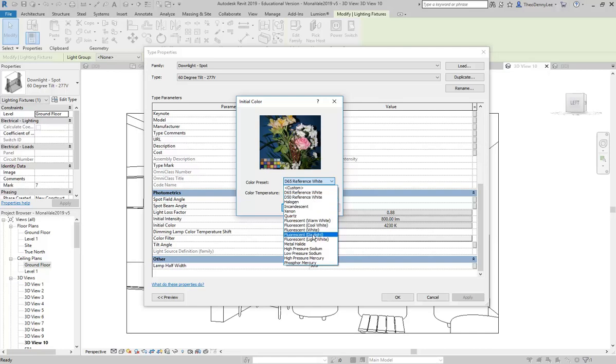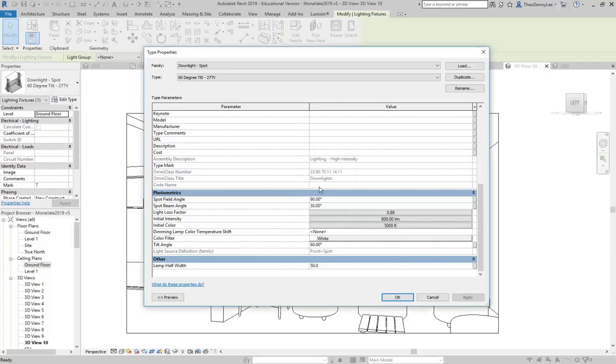So here if we go fluorescent daylight, I bet you that'll be too warm. Oh no, that's cool. Names are funny. Light white, what am I saying that is? That's a warm one. Warm white, that's really warm. Cool white, well see there, cool white is not that cool. But that's from the fluorescent, which, well, fluorescents were always really cool, but this is what they've called them. But as long as you've got an idea of the temperature range, then you can adjust the colour of your lights in that warm to cool range.